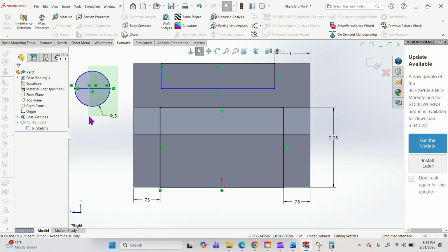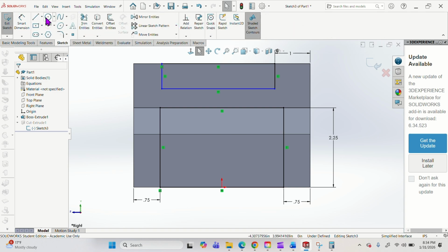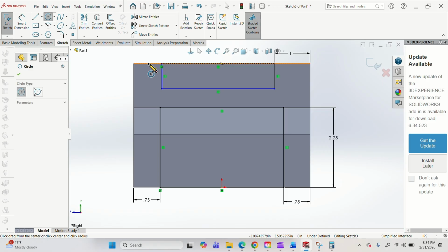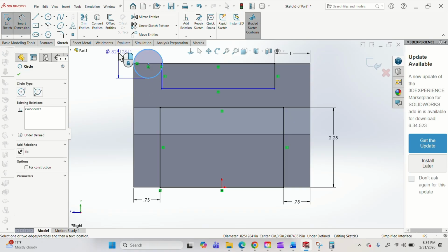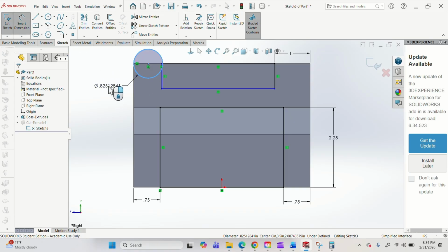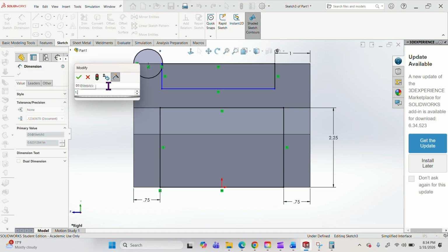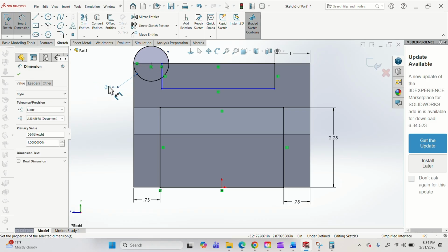Now, you could have just drawn it off to the side to figure it out. What you could have done was take a circle and draw it at the size you needed, or just draw a circle. Make sure it's coincident to the edge because you know your arch is going to go this way. Give it your dimension, which would be a 1-inch diameter.